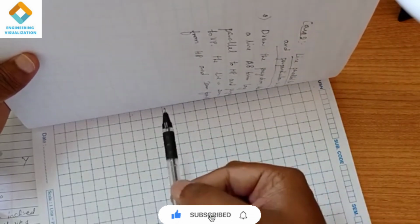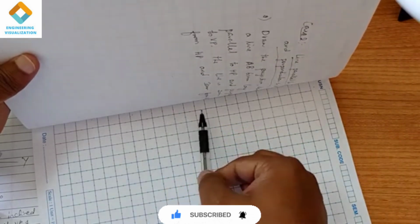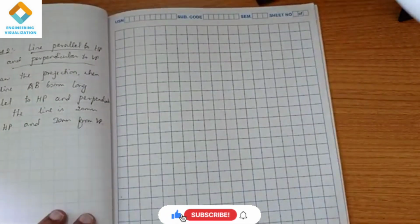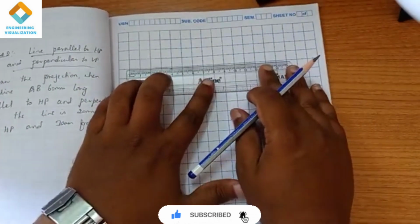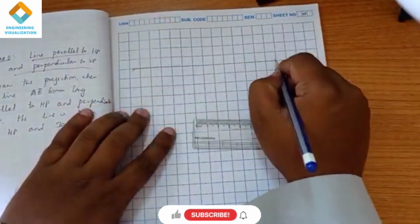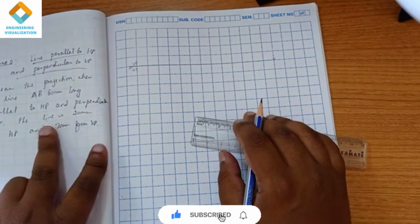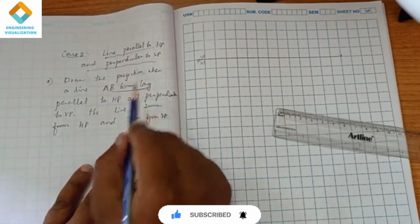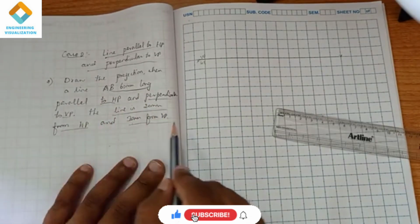Perpendicular means you will get a dot on the vertical plane, and there is a straight line in the HP plane. This is what parallel to HP and perpendicular to VP means. Like this we have to do it. First we draw an XY line, with VP and HP, using the first quadrant. Line AB is parallel to HP and we have to make it perpendicular to VP. The line is 20 mm from HP and 30 mm from VP.